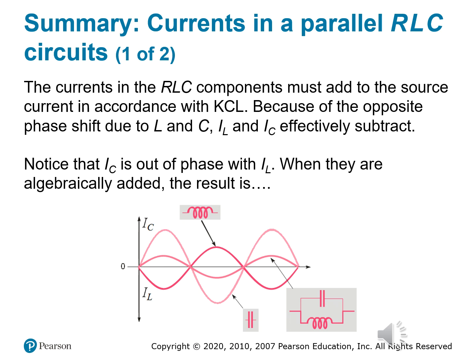What happens when these two phasors collide? Well, they subtract, not destructively, but constructively, revealing the leftover current that contributes to the total. The visual here is pretty powerful if you're looking at waveforms. The capacitor's current crests early, and the inductor's current drags behind. Together, they create a dance that aligns beautifully with the resistor's straight and steady path. This subtraction by phase is how we unlock the total source current. That's just the current your generator would actually supply.